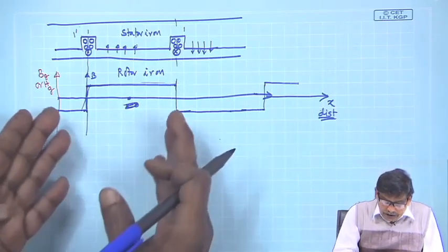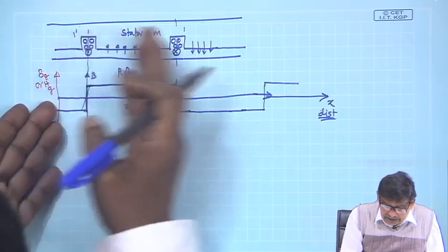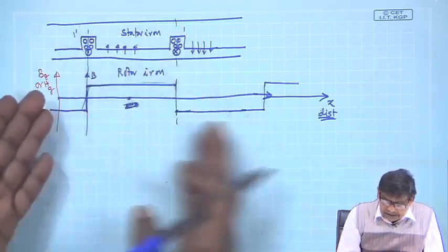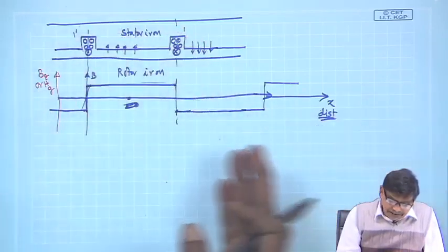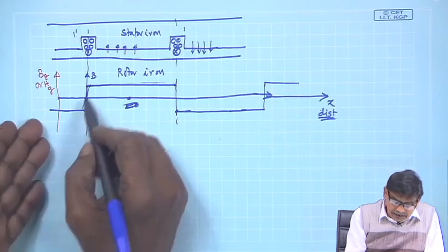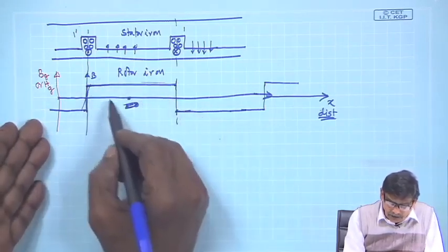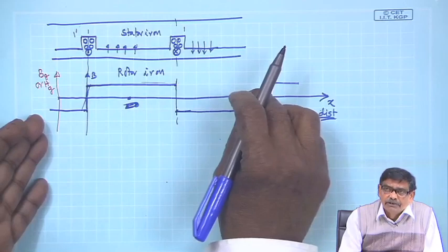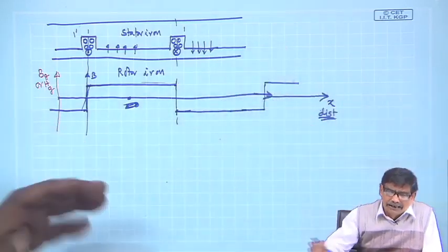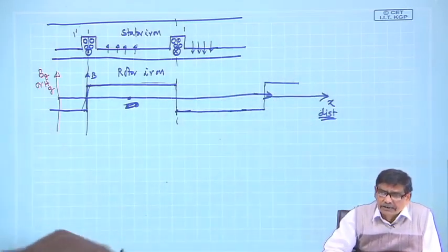But it is not going to be, as we are seeing a single coil like this. At best you can say okay, it has got a strong fundamental sinusoid with a lot of odd harmonics with reduced amplitude. Perhaps you can neglect those and only fundamental you can say.